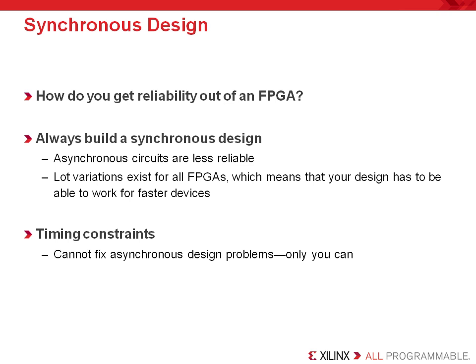I have also seen cases where customers will try to change their internal delays to meet an asynchronous design problem, with the hope this will get the design to work. It may work for a while, but there is no telling how long it will last. So the simple rule is don't expect timing constraints to fix your asynchronous design problem. Build the design properly and it will work. Let's have a look at some of the synchronous design methodologies.